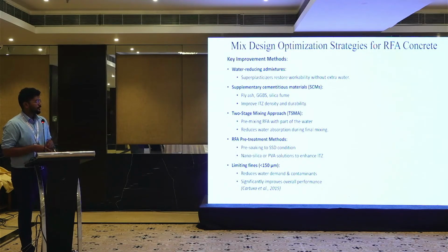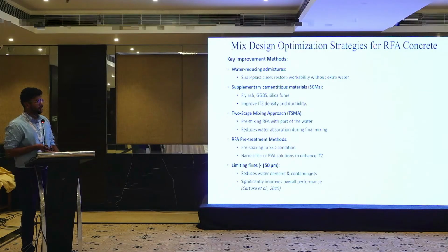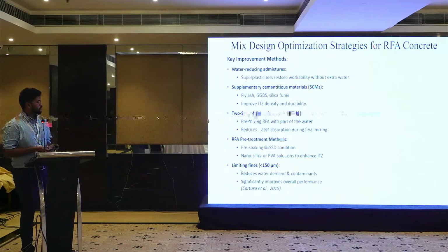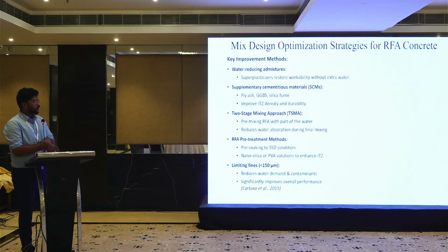pre-mixing the fine aggregate with part of the water, then adding cement and the remaining water, to reduce water absorption. Also pre-treatment methods: pre-soaking to saturated surface dry condition, and nanosilica or PVA solution to strengthen the ITZ. Limiting fines: we can limit the fines to a level of 150 microns, reducing water demand and contaminants.